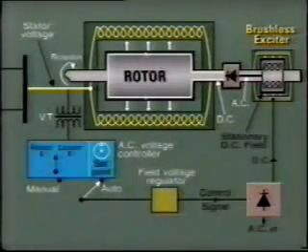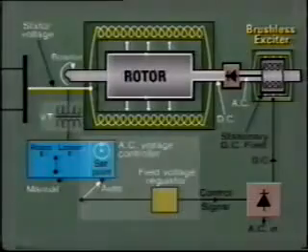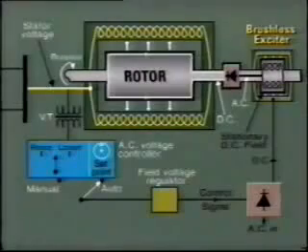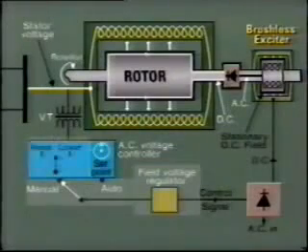The arrangement at this point is similar to the static exciter. When in auto, the field voltage regulator receives its command signal from the AC voltage controller, which in turn monitors the output voltage of the generator. The operator can adjust the AC set point as required. When starting up the unit, the field voltage regulator may be set to manual, and in this case the operator will control the regulator directly.